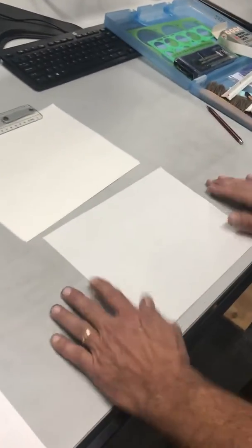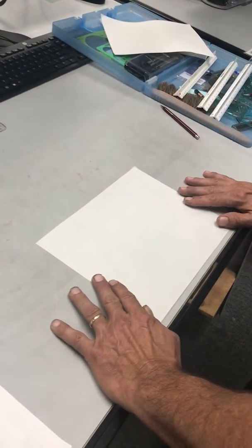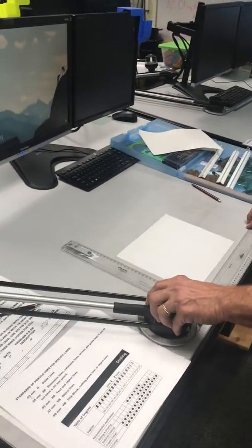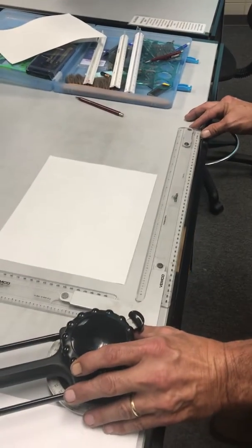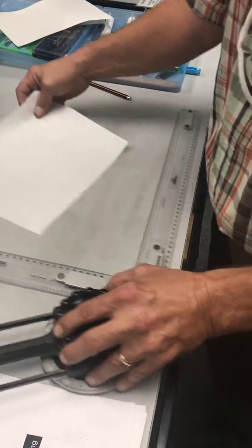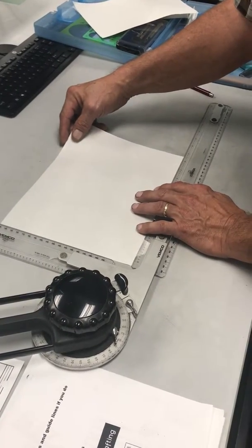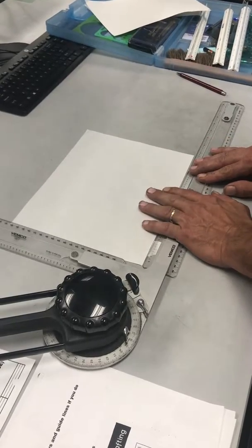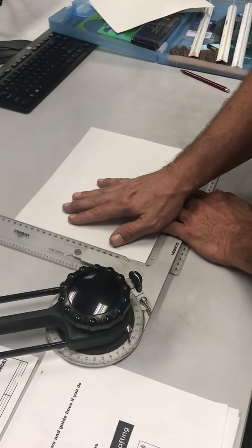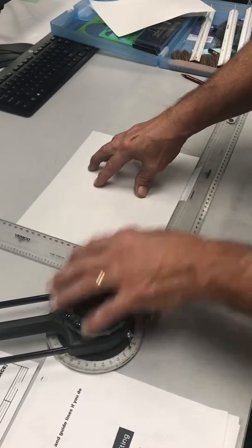All right, so what we do to get this paper square, I normally bring the drafting machine down. We have drafting machines in the lab. I bring it down, make sure the drafting machine is square against the bottom. All right, if it's square against the bottom, then I can go ahead and bring it up. If you're a left-hand drafter, you're just going to do the opposite of what I do here. So I'm going to get this paper where it's square off the bottom and then square vertically, like so. And then I'm going to move away from it.